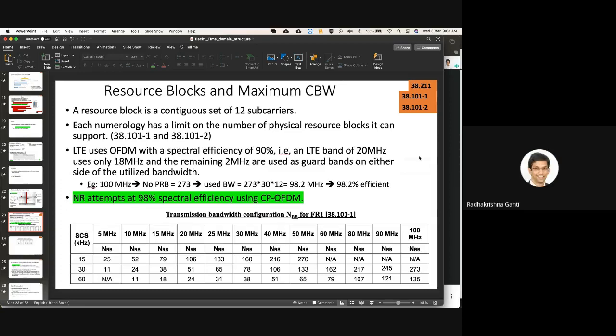Another important thing that came up is uplink MIMO. This is the main reason, because in uplink also we are using MIMO. So CP OFDM is very good for that. MIMO plays very well with CP OFDM, whereas single carrier OFDM and MIMO don't get along well. I mean, you can do MIMO there also, but it's a little bit more difficult. So these are the reasons why people have chosen CP OFDM. There's also an option of SC-FDM in the uplink.